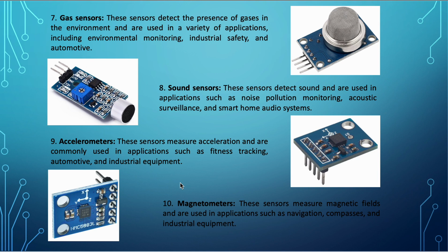Then you will see what kind of sound you want to check. It could be ultrasonic, it could be something that only dogs could hear, it could be something that humans could hear, or something that humans under some age can hear, right? So depending on the frequency, or depending on the requirements, you have to check the properties of the sound sensor before buying the product.